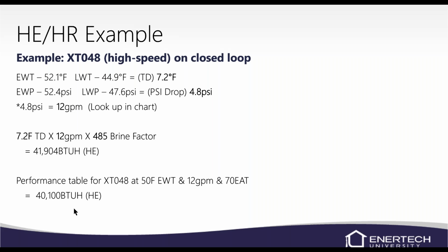Maybe we're not really moving 12 GPM. Maybe we're really moving 11 GPM. But we're within 10%, so there's really no reason to worry about doing anything else. As long as it's 10% above or below this IOM number, then we're good to go. There's no need to put refrigerant gauges on and try to diagnose the system. The system is doing all that it can.